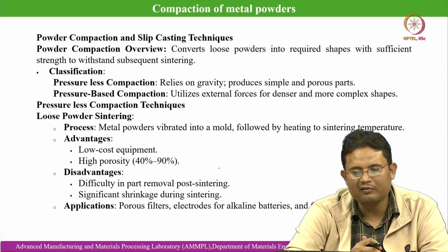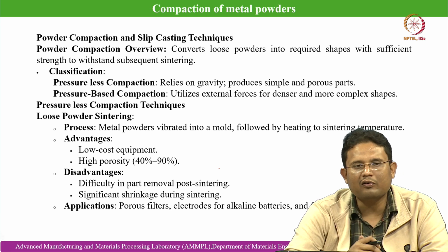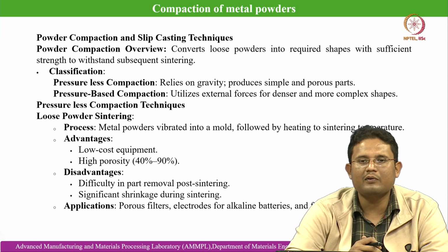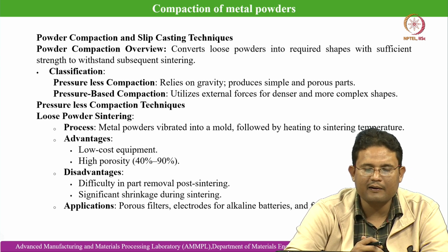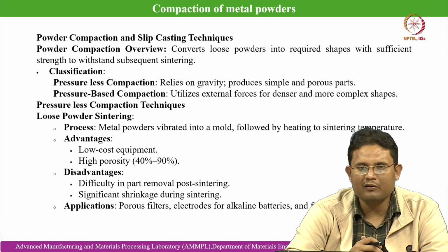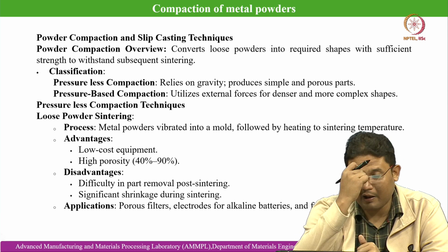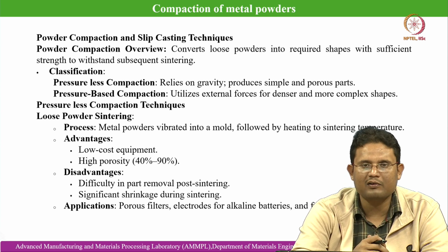The disadvantages are difficulty in part removal post sintering in case of loose powder sintering, and also significant shrinkage during sintering. Compensating for the shrinkage achieved during sintering is important in case of loose powder sintering, because otherwise it can cause significant distortion, and then the resultant part may not qualify for its intended application. So that needs to be accommodated in the desired part geometry, that enhanced shrinkage happens due to loose powder sintering.